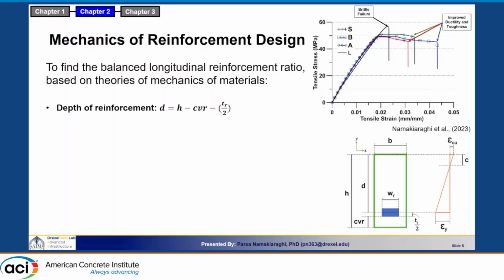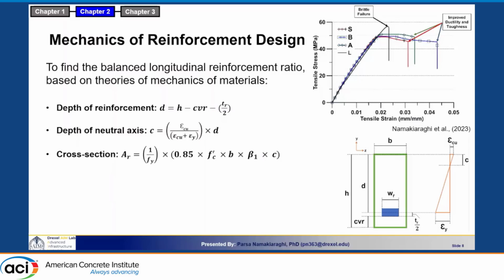So basically, based on the ratio of the strain of our different materials, which on one hand we have the polymer reinforcement, and on the other hand we have our cementitious composite, we needed to establish what's going to be the depth of reinforcement, to find the neutral axis, and furthermore the cross-sectional area that we need to reinforce.